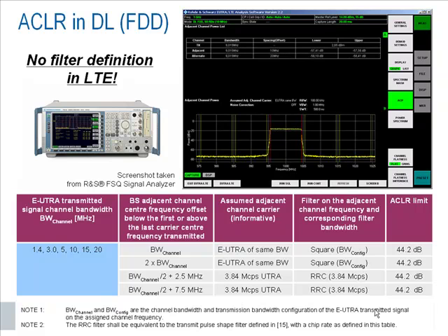In case of LTE FDD, first, the presence of another LTE signal with the same bandwidth is assumed. Second, a wideband CDMA signal is available. The general limits are shown for both cases in the display table. Based on the used and tested frequency band, additional requirements in form of lower tolerances might be valid. This would be signaled to UE via network signaling and needs to be verified during testing. Such tests can be performed using Rohde & Schwarz high-end signal analyzer FSQ, where the screenshot is taken from.